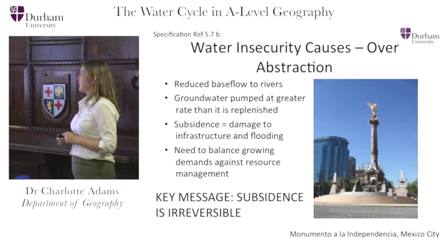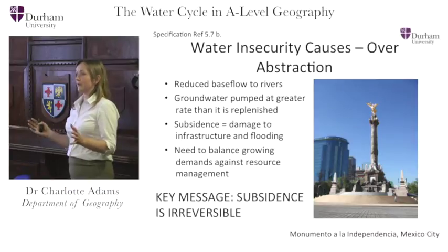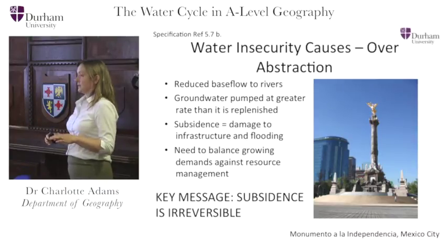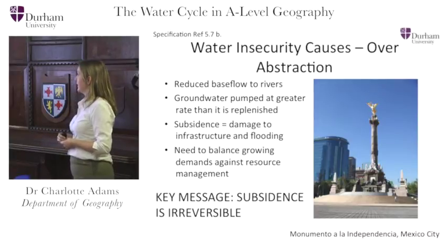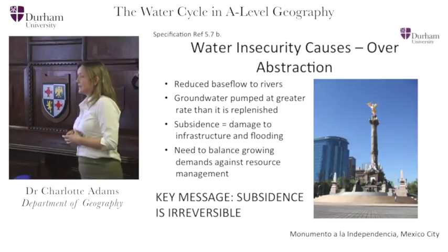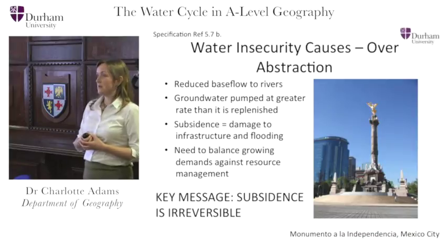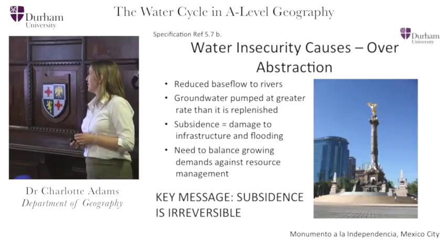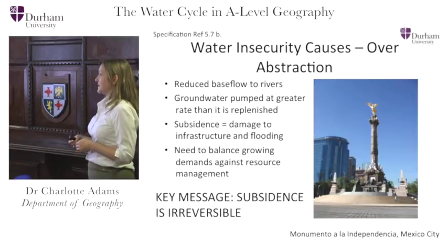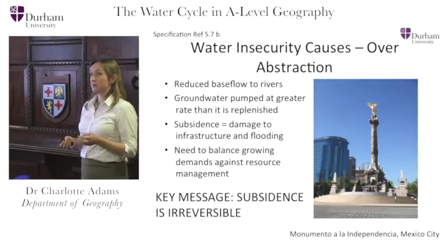The upshot of that was that in 1950, pumping from the central part of the city was banned and moved to the periphery. So the central part did stabilise, but in the outlying areas there's still subsidence going on. This statue that was built in 1910 didn't subside, but unfortunately the land round it did, to the extent where they needed 23 new steps to be able to get up to it. That's the least of your worries because of the other impacts it's had on buildings and rail infrastructure. There are problems with it in China.